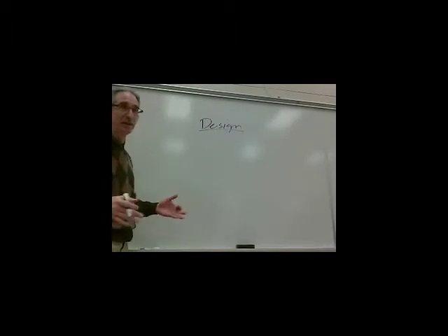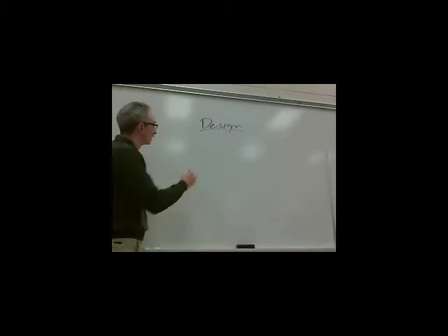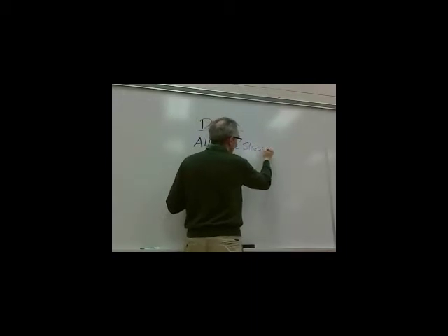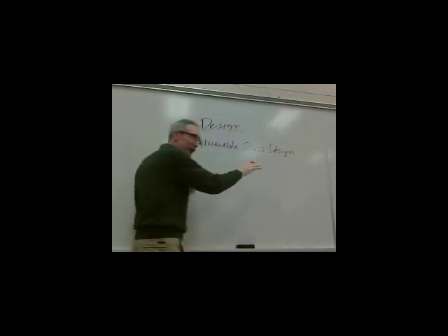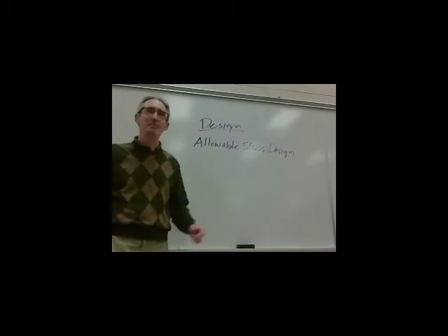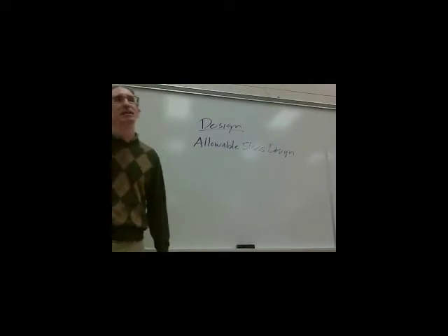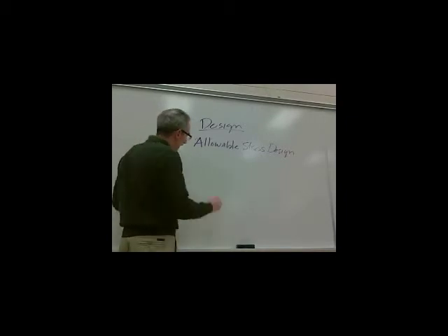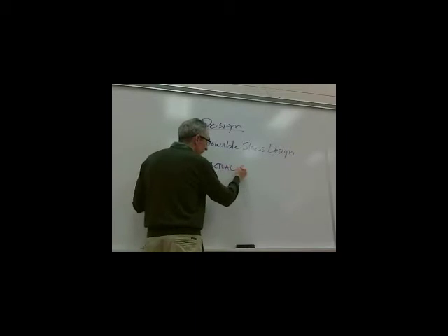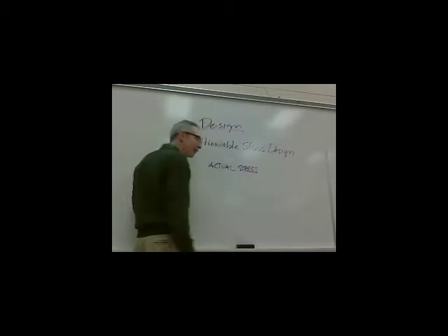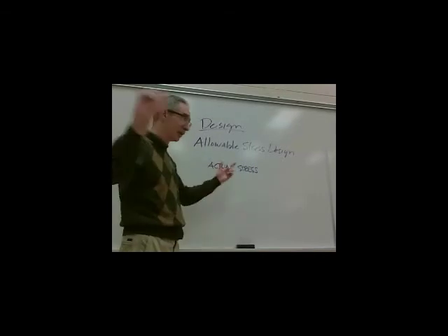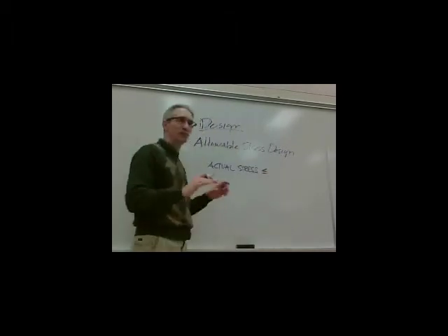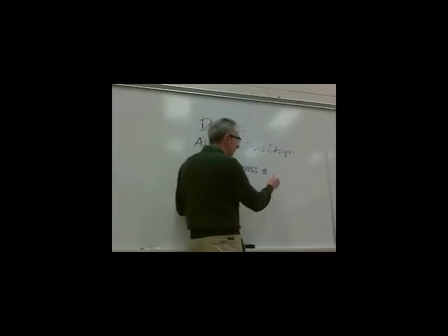One method that's out there, and it's one of the oldest methods, is what they call allowable stress design. I'm not going to talk about any particular material that might use this, but I'll just talk about this design method because it's a really easy method to comprehend. This method basically says this: if you can calculate your actual stress, and the code that you might be using, or maybe your teacher, gives you a stress level to stay at or under, then you're going to be okay.